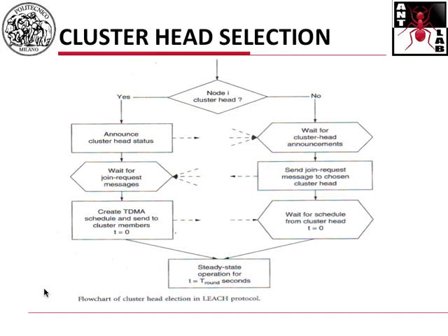If it's a cluster head, meaning if it has drawn the random number and this random number was below the threshold, then it elects itself as a cluster head, and what it does is start announcing its own cluster status, which means that there is one specific message for cluster head announcement. It's a broadcast message, which is basically telling the other nodes, look, I am a cluster head. If you want, this is kind of equivalent to a beacon slot, a beacon message in a 15.4 implementation.